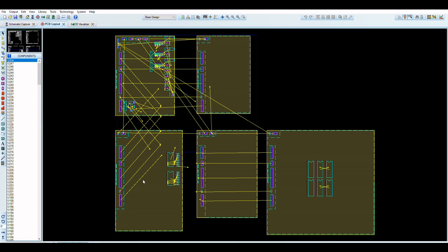It starts calculating Sprite pixels on one scan line while it's outputting the other scan line, and then it flips all of the logic around and does the other half. So we actually have two scan lines, one being updated and the other one being output to the video, alternating in that fashion. It's actually a very efficient use of memory. It means that you do not need to have full RAM for two screens. You can just have two scanline buffers.